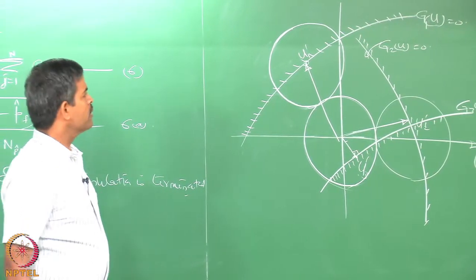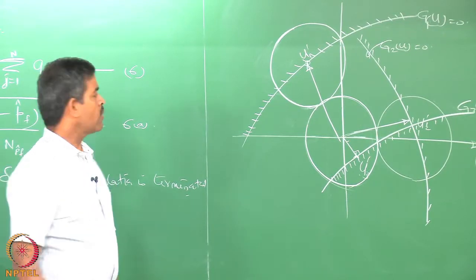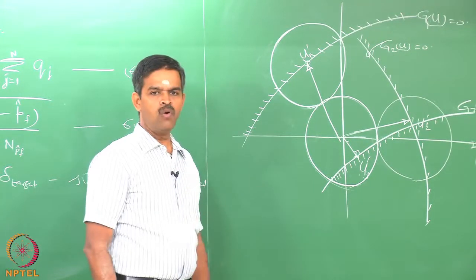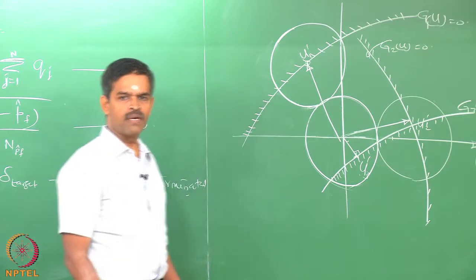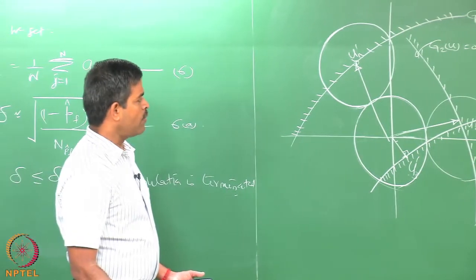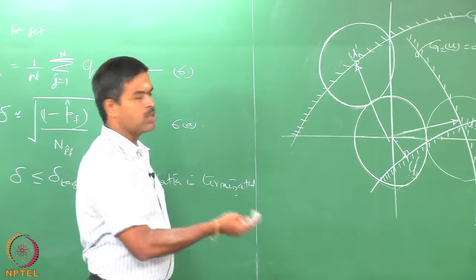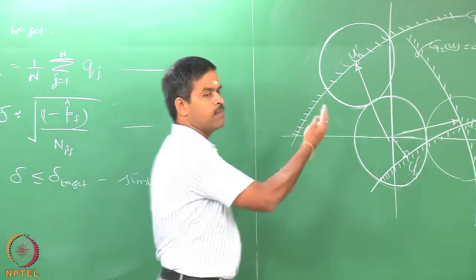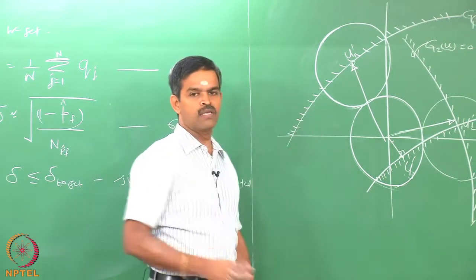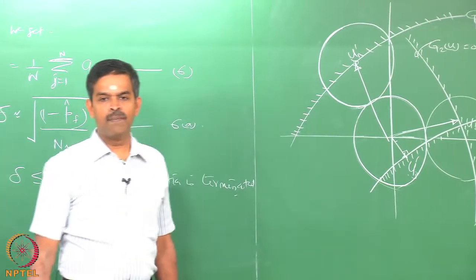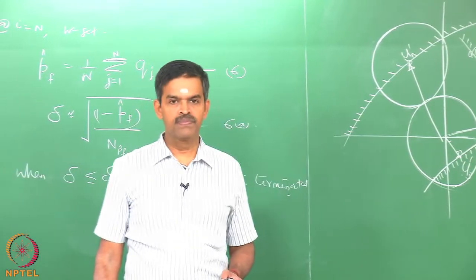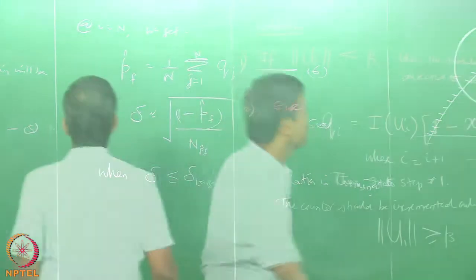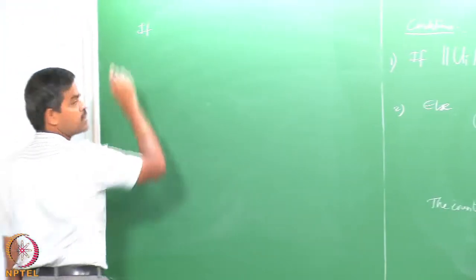So, one should be able to really know if you have got multiple design points like this, how do we actually able to get a good sampling, because one can always land up in either U1, U2 or U3 depending upon what is the failure envelope, and the failure envelope is governed by the choice of your sampling density function h of x.